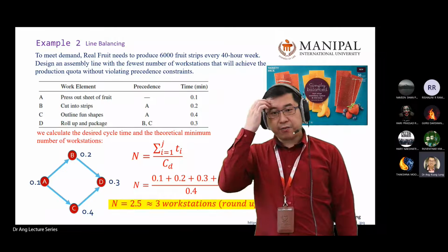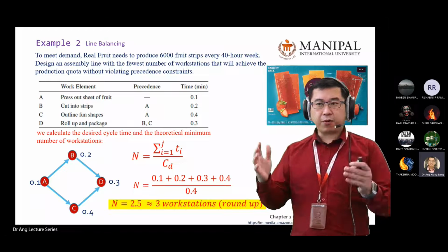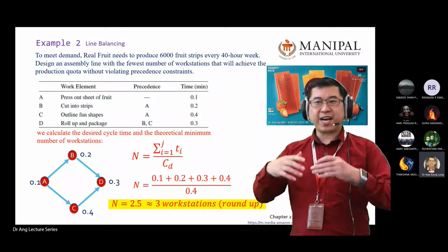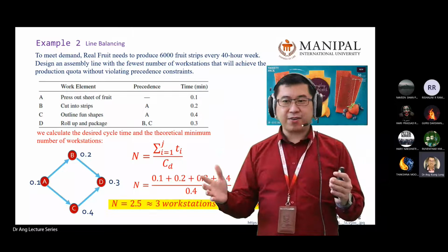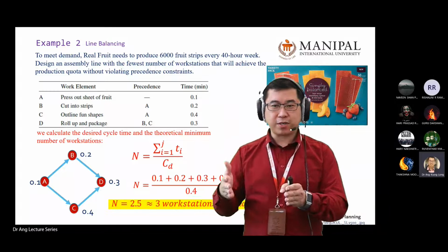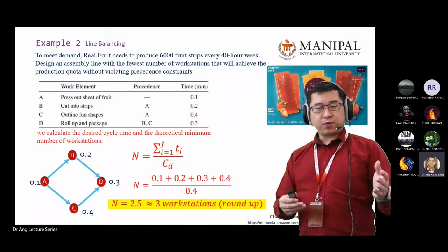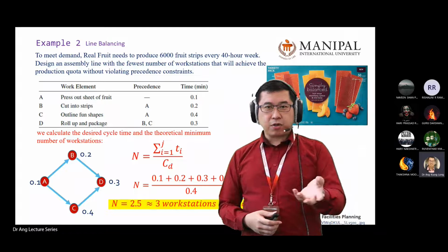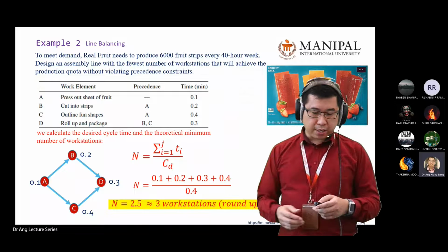So you imagine if you calculate 2.2 or maybe 4.2, you need 4.2 workstations. You can either have a full set of 1 workstation or no workstation at all. You cannot build 20% of a workstation and then put it there. Your worker will be confused: why does this workstation only have 1 screw or 1 spanner there and it's not complete? So it cannot do the job. It's meaningless. So always use the next full number.